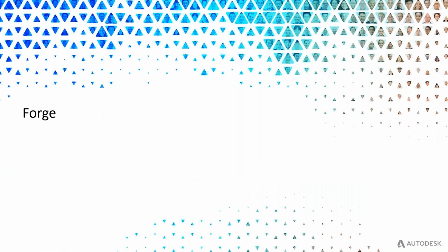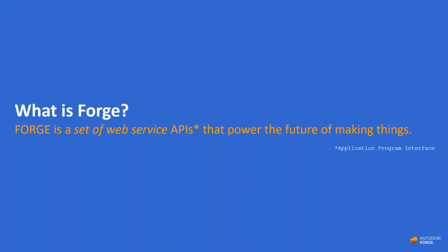So we're going to use the API to connect to just about any database that is out there and that we need, maybe because there's other information in there, maybe that's an ordering system and we need to understand how this is coming through into our models. So essentially we're going to be using Forge for that. And Forge is the API of BIM 360, which essentially means that anything you do inside of BIM 360, you can automate. It's a bit like the API for AutoCAD or for Revit. Anything that you think of that you want to do with Revit in an automated way, for instance, generate sheets automatically, and I'll get to that in a second because that's quite important from a Forge point of view. Actually, we can do that with Forge on BIM 360.